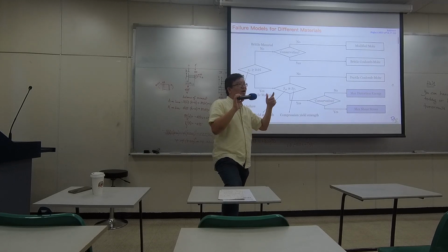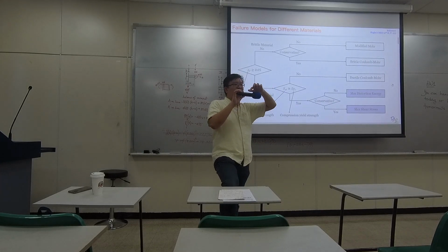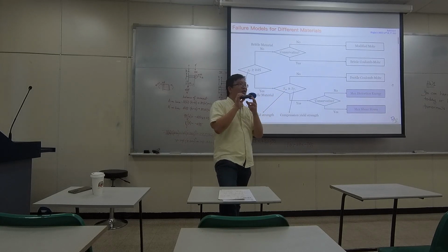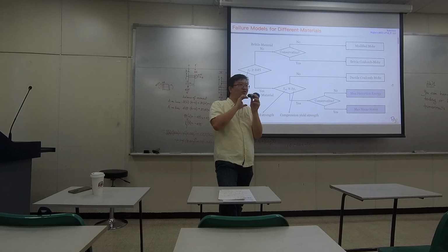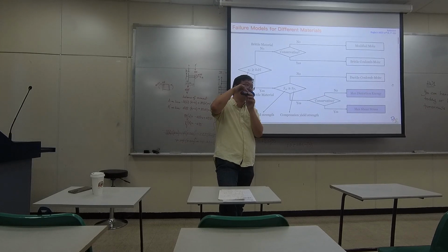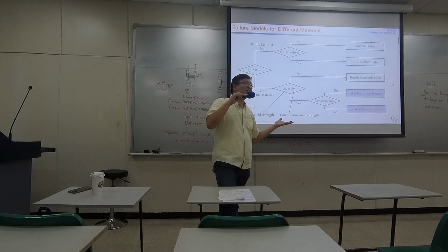If I apply the stress equation for the top, it's going to be moment times the radius over the area moment of inertia I, so MC over I. That will be the stress on the very top. When I do the same thing for the bottom, same equation, MC over I.